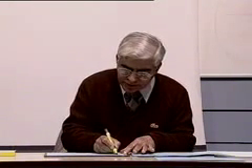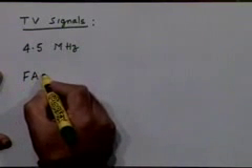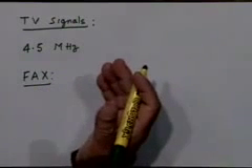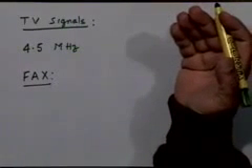And that's precisely what you do in a facsimile signal. And that's the reason I can transmit a fax signal through a telephone line, which is designed to carry only 4 kilohertz of bandwidth, because the rate of scanning is under my control, and there is no particular hurry, from the point of view of the nature of the picture that I want to transmit, to scan it fast. Of course, if I scan it fast, there is an advantage.